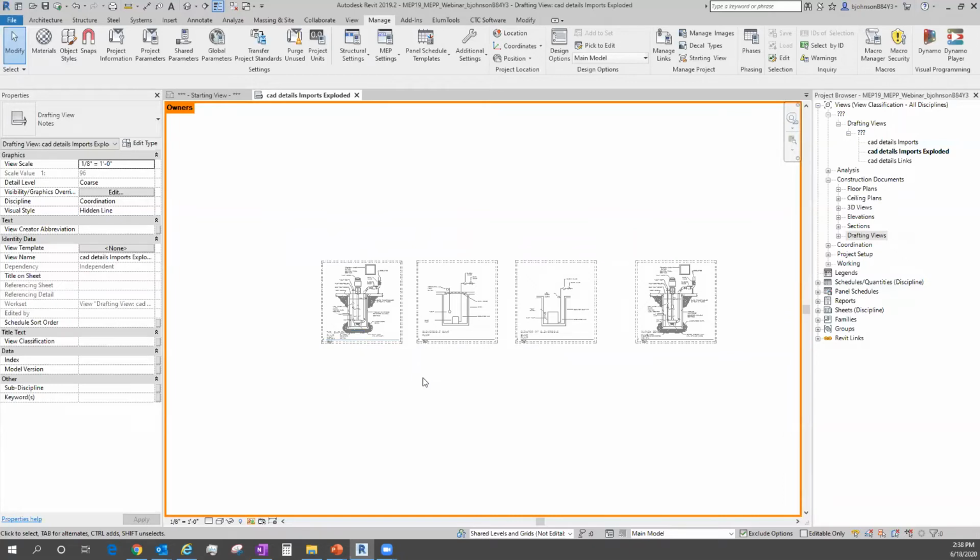A lot of times you want to reuse content from old jobs that aren't in your master library, but I'd still do at least a cleanup Revit file within the project folder. Do all that cleanup work there and then place them from that file instead of your master detail library into the current project. So you get the same information, but have it cleaned up.